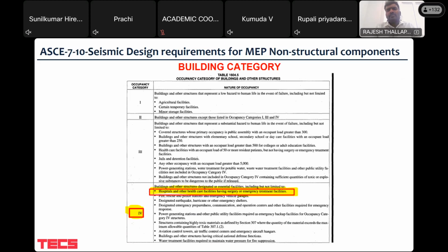What happens is that when any natural calamity happens, either an earthquake or tsunami or whatever, or a fire accident, any structure can get damaged, but life safety structures like hospitals or fire stations or any other life safety related structure should be intact, so that whatever damage happened due to this natural calamity, people will go to the hospital and have access to life and healthcare. So this is the reason it was given a category 4; the more important buildings fall under the higher categories.